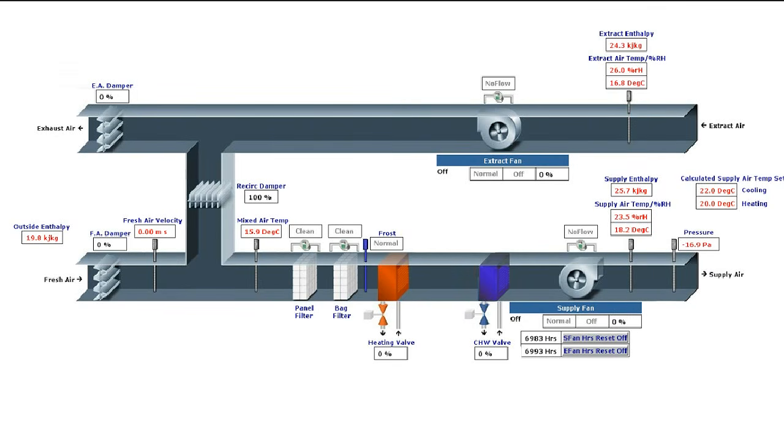Now, I've talked a lot about the BMS, the building management system. This is just a screenshot from a typical BMS of the system we drew earlier, the one I've made a model of. This is what it might look like on the computer screen. There'll probably be a bunch more readings around here. I've taken some of these out just to clean it up and let you see what it might be measuring. So here again we've got the dampers in their position, so it's measuring these.